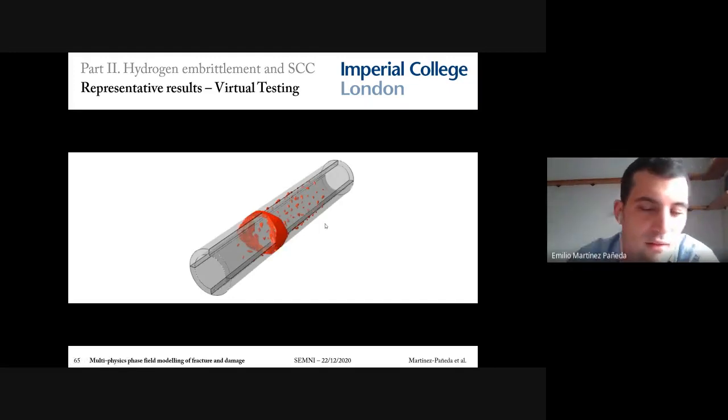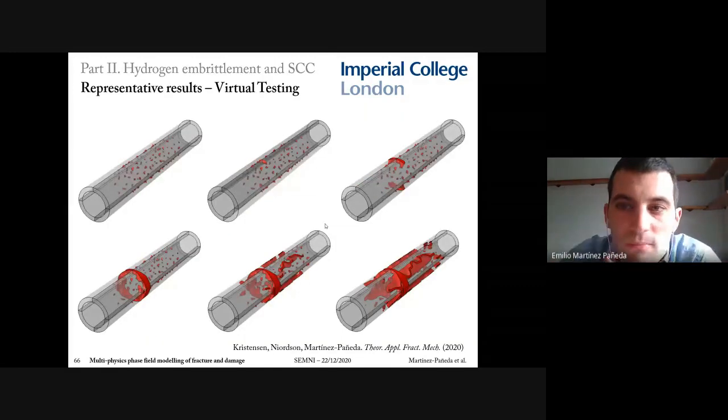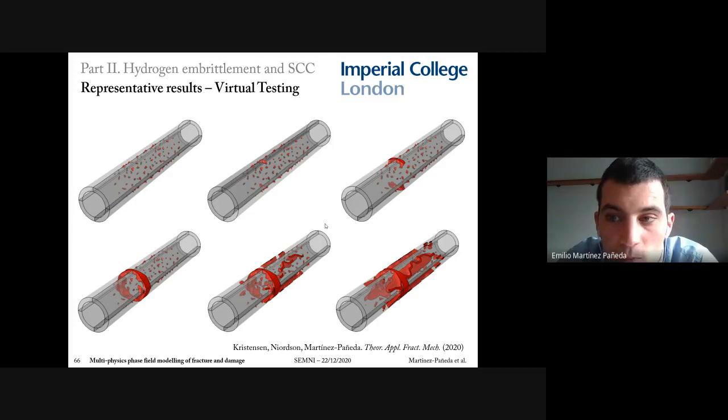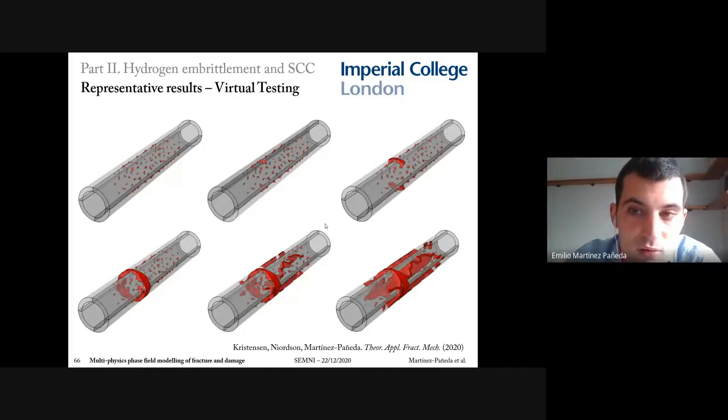So this is loaded at conditions mimicking a riser. And this looks a little bit like a video game, but I should emphasize that it's a sophisticated multi-physics model. Everything is computed on the regional finite element mesh in an implicit backward-Euler framework without any convergence problems and fully parallelized, such that it can run in a few hours. So we have a tool that allows us to know how the crack will propagate and when it will propagate, such that we can decide when to replace a component or what the limit service conditions are.